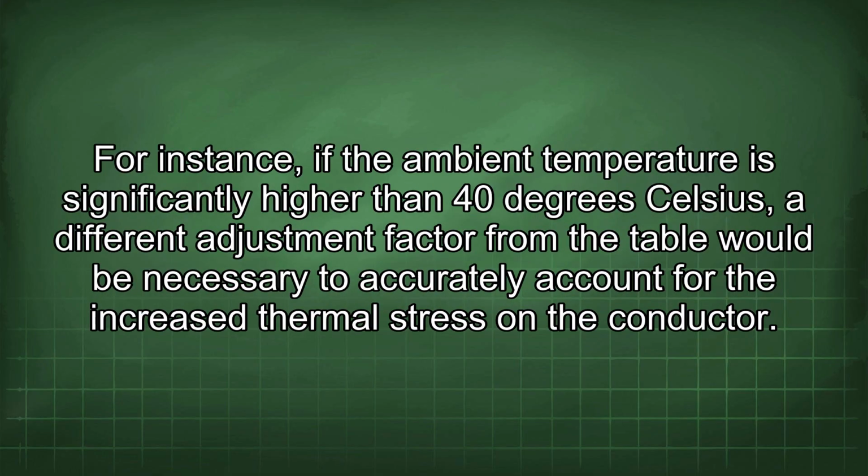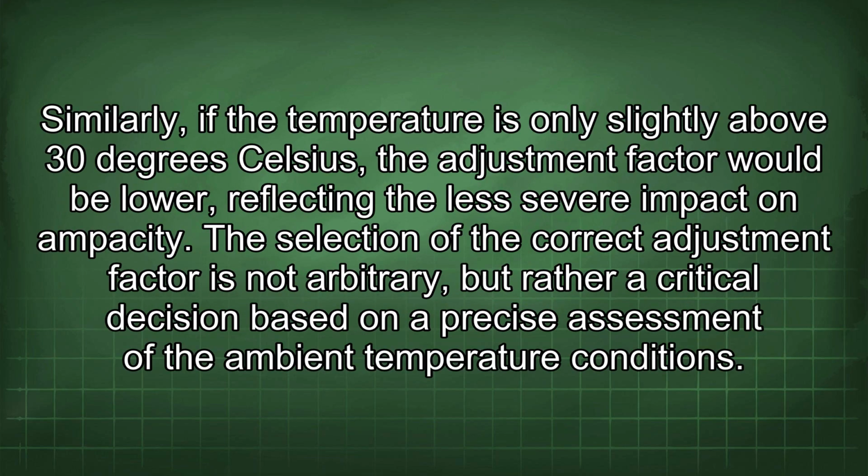For instance, if the ambient temperature is significantly higher than 40 degrees Celsius, a different adjustment factor from the table would be necessary to accurately account for the increased thermal stress on the conductor. Similarly, if the temperature is only slightly above 30 degrees Celsius, the adjustment factor would be lower, reflecting the less severe impact on ampacity. The selection of the correct adjustment factor is not arbitrary, but rather a critical decision based on a precise assessment of the ambient temperature conditions.